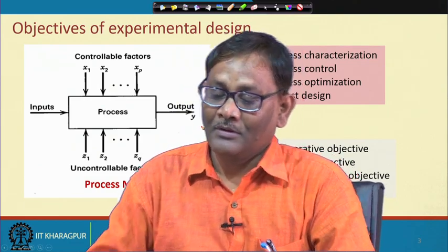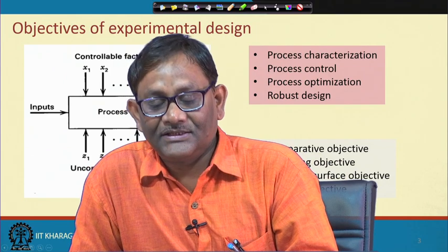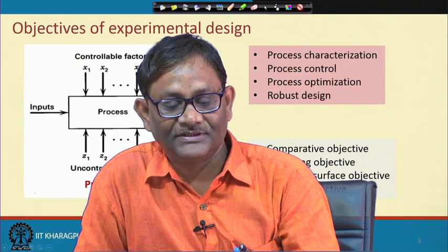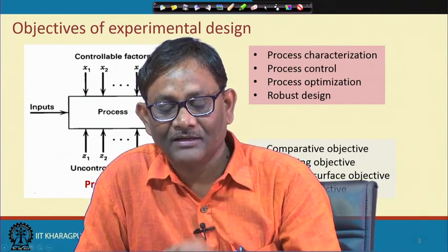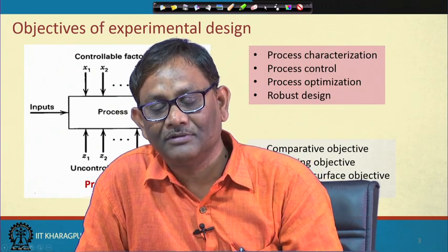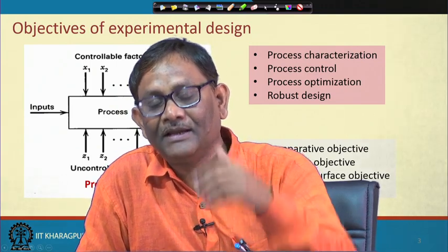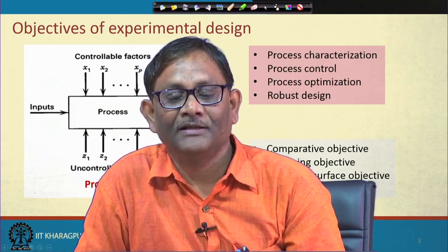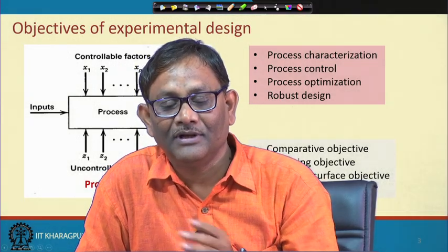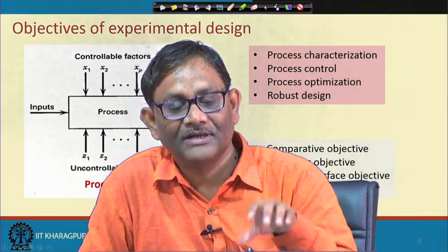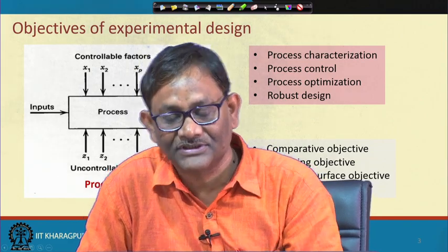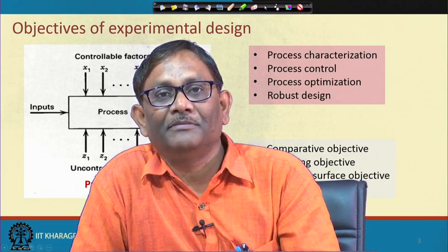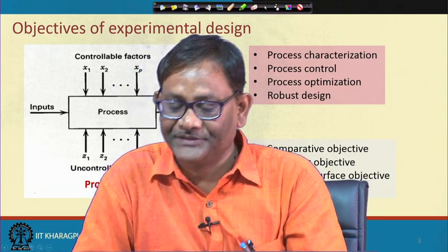Now, in this response surface case, we may be interested to know where the optimum response lies. What does it mean? It means what the settings for the control variables should be, so that we can achieve the optimum desirable value of y, and then the process operator will set or tune the parameters of the process in that range, so that the optimum y will be achieved.